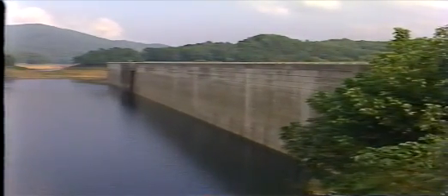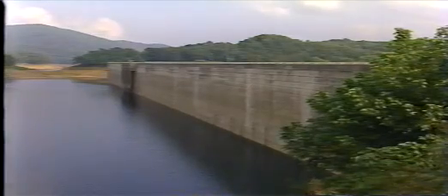Check for cracks, concrete deterioration, and displacement. Try to identify cracks that may be the entry points for any leakage observed in the galleries or on the downstream face. Also keep in mind that the level of the reservoir influences such factors as leakage rates and crack openings. So note the level of the reservoir at the time of your observations.